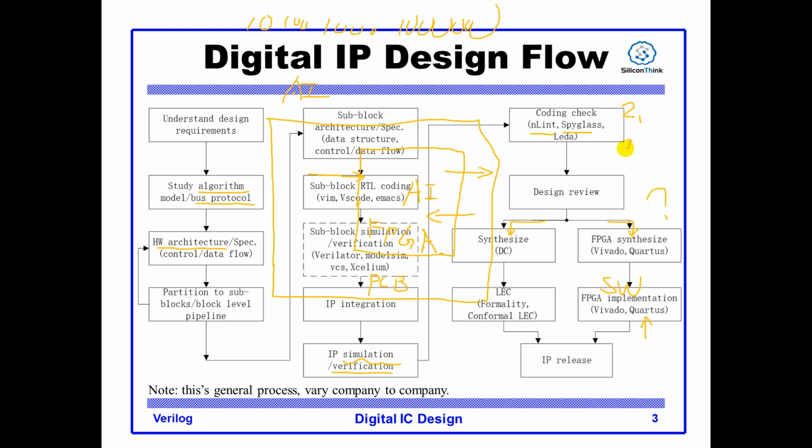And the third is, the software team will be involved in an early stage of the design process. If you don't do FPGA emulation, when can the software team get involved? Yes, they can only get involved after the tape out, when the chip is returned. So this is a very late stage in the whole design process.